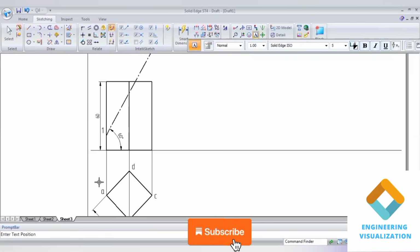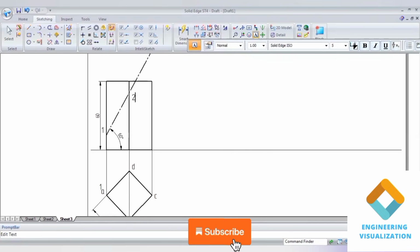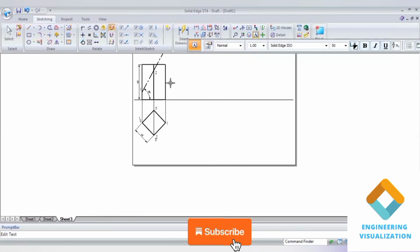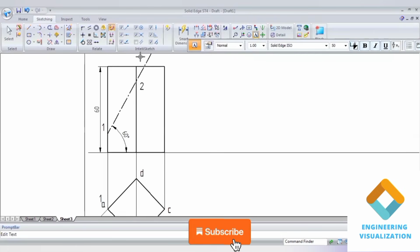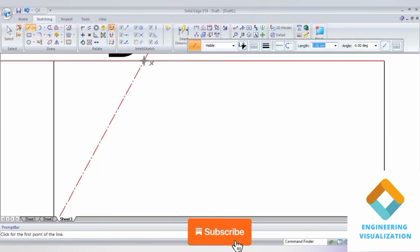Now we can give the naming here. So that is 1, where it is cut. Again on the A point it is 1, again here the same on the A edge. Now point number 2 is falling on the vertical edge B. And then point number 3, you can see it is not falling on C, it is falling somewhere in between B and C.